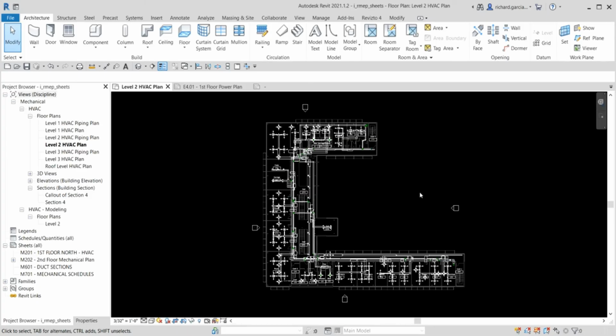Anyway, after learning the basic stuff of title blocks, in this exercise, we're going to create a sheet and modify its view properties. And then we are going to place a plan view and a section view on our sheet and specify the print option if you want to print it. Okay, so let's try this one out.